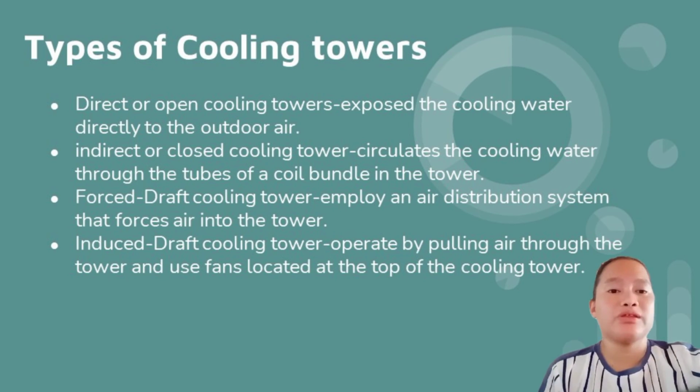Types of cooling towers. First is the direct or open cooling tower. It exposes the cooling water directly to the outdoor air. Second, indirect or closed cooling tower. Circulates the cooling water through the tubes of a coil bundle in the water tower.